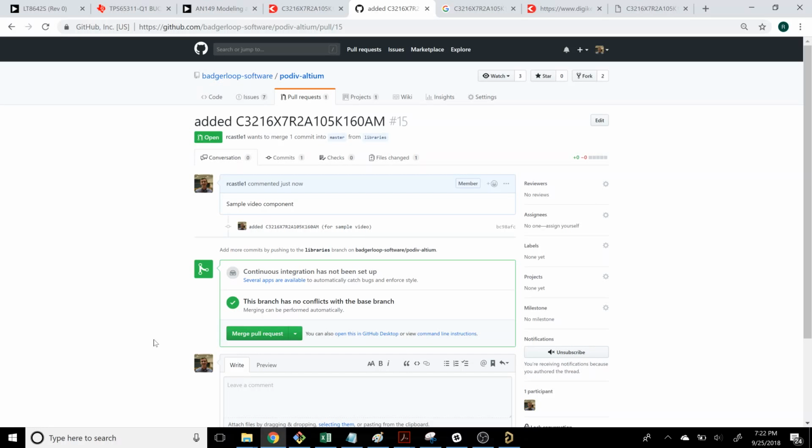So you can ask myself, you can ask Tristan, you can ask Vaughn, or anyone else who has some experience with Altium, and will want to do some checks of your components to make sure that they're valid. So for something like a capacitor, if you get a datasheet link wrong or you say in a description that it's an 0402, but it's actually a 1206, like I did earlier, and you don't catch it, it's not the end of the world for something like a capacitor.